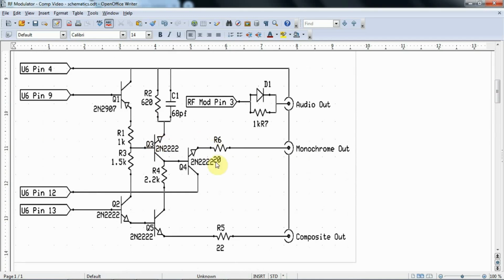I found this circuit, and I'm pretty sure this needs to say pin 11 and this needs to say pin 12, because pin 11 is the 5-volt VCC and pin 12 is the modulator output. And notice it matches the first circuit. If this was pin 12, it goes through the 2 emitter followers and the 22 ohms, and that's composite out.